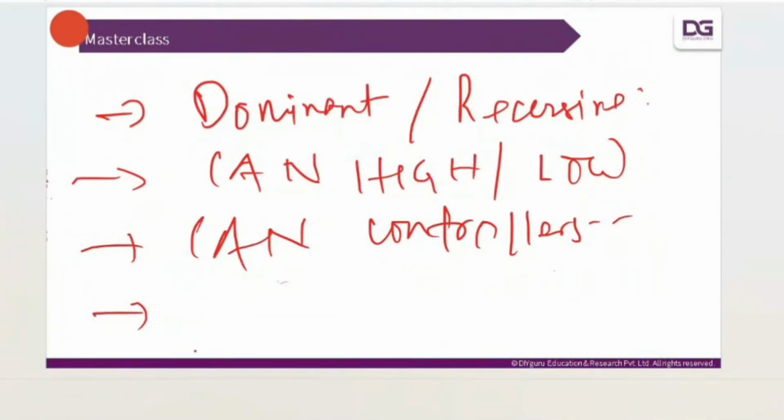When you are targeting any protocol, first of all, the frame is important. You should know whether it is asynchronous or synchronous, whether it is address-based or message-based, whether it has master-slave concepts or not, and the different types of frames we can see in the protocols.